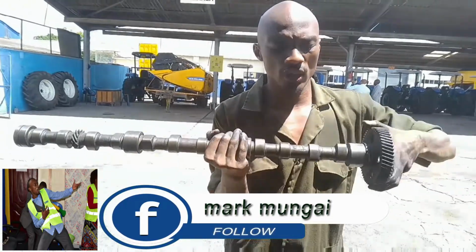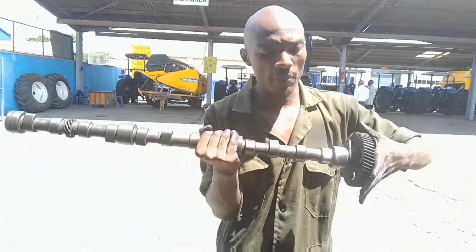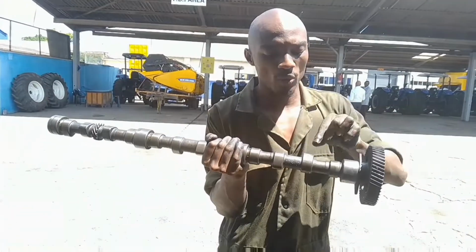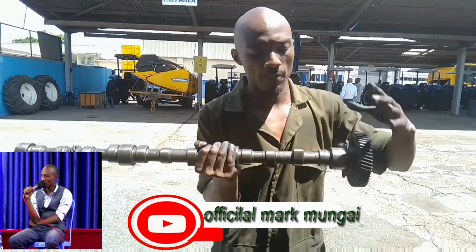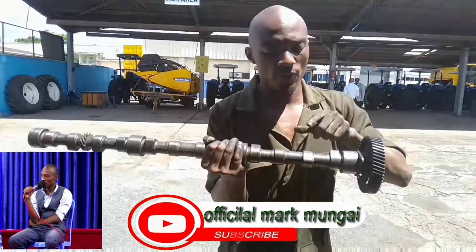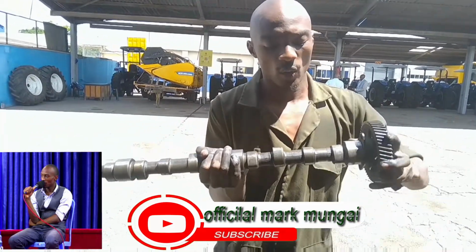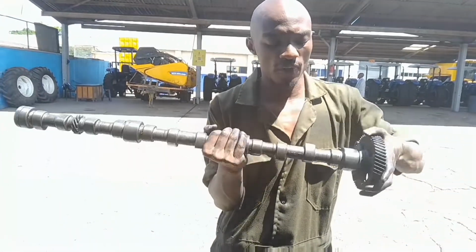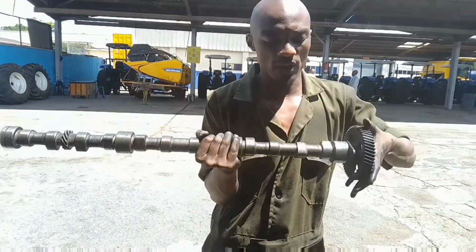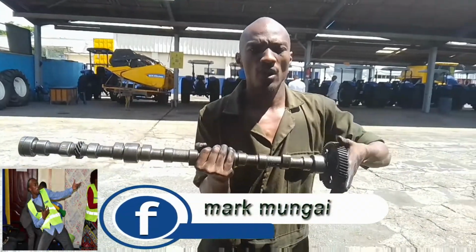So when you are told to draw the cam profile, you're simply going to draw how the cam is rotating the follower like this, because the follower has to be on this part. So when it is like this, the follower is lifted up. When it is like this, the follower is on dwell. When it is like this, the follower is still on dwell. When it is like this, the follower now has a return stroke. So we have the out stroke on the right, we have the dwell, then we have the return stroke, then we have the dwell, and then we have the out stroke.